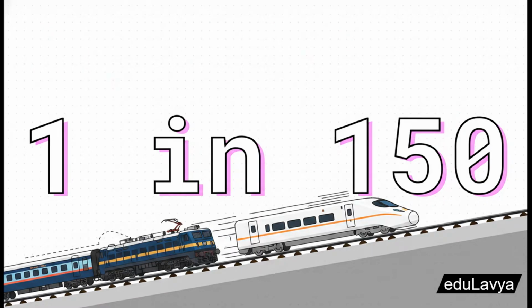For instance, the design for Indian high-speed corridors proposes a ruling gradient of 1 in 150. Why such a gentle slope compared to Europe? Because this specific gradient allows existing, much heavier conventional passenger trains, like the Rajdhani or Shatabdi Expresses, to actually share the high-speed line if absolutely necessary. It ensures their heavy locomotives won't just stall out halfway up a hill.